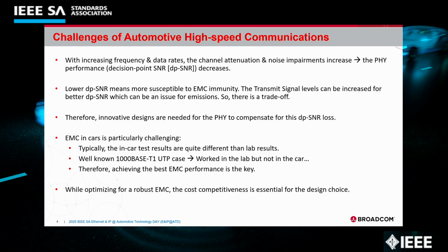As the channel attenuation and noise impairments increase with the increasing frequency and data rates, there is an impact on the PHY performance. Lower performance means more susceptibility to EMC immunity for the PHY. So there is a trade-off that can be attained by increasing the transmit signal levels, but that can be an issue for emissions as well. Therefore, innovative designs are required for the PHY to compensate for this loss.